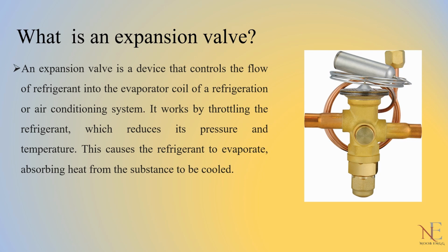Okay, what is the working of an expansion valve? So basically, this is an example of an expansion valve that we are going to study in our syllabus. At the right side, this is a thermostatic expansion valve. Okay, but what is the purpose of an expansion valve? What does it do? It simply reduces the pressure, as well as the temperature, of the liquid refrigerant while it enters the evaporator.